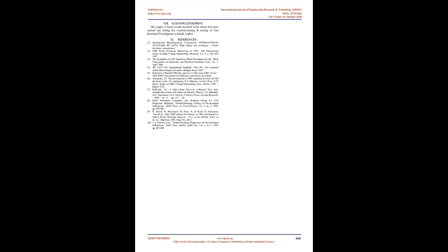7. Conclusion. The monitoring of partial discharges is done perfectly with the help of the above-mentioned system using the optical units, control cabinets, and distribution cabinets. The accuracy of monitoring the PD activities is essential for the early detection and prevention of faults on gas-insulated switchgears, by which the equipment is also saved from being damaged, which might result in huge loss. By using advanced communication and control systems like the substation automation system, the monitoring is done easily from the far end remote control centers. Hence the GIS is protected from damages and blackouts, and thus the stability of the power system network is maintained.